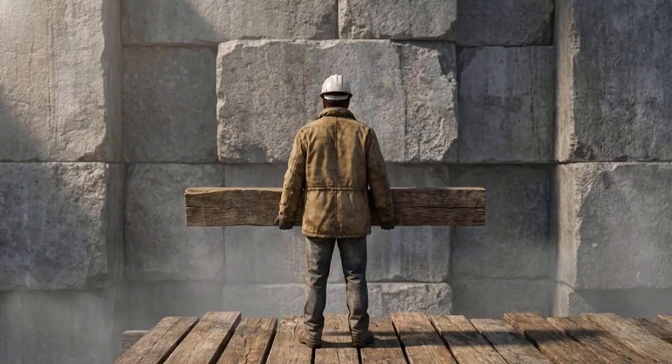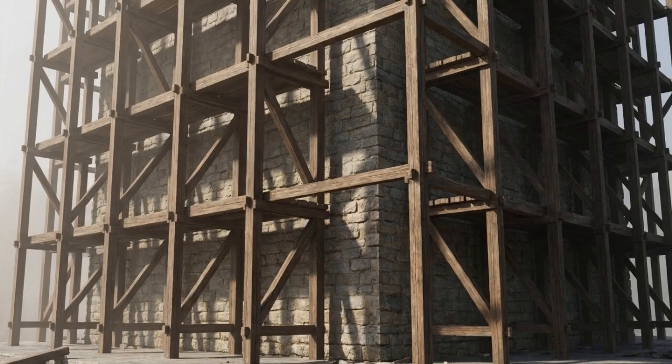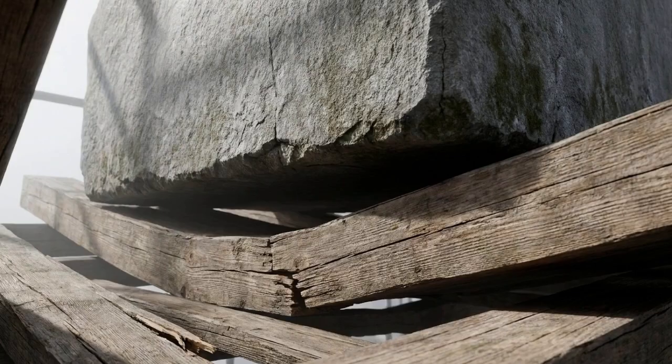When construction shifts from small bricks to massive, impenetrable blocks of solid stone, the physics change. Builders can no longer leave deep putlog holes inside the load-bearing facade. To solve this, engineers developed the mason scaffold. It is a framework completely detached from the wall, designed to carry extreme crushing weight without penetrating the permanent architecture.